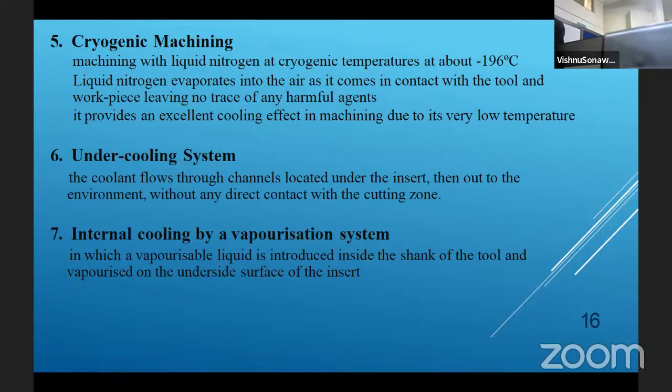Due to the very low temperature and excellent cooling effects, this cryogenic fluid will be used for cryogenic machining up to minus 196 degrees Celsius. This is the main important aspect. Then cold machining, right? Under the cooling system, the coolant flows through channels. These channels are the air channel and the oil channel. These two channels are fixed.